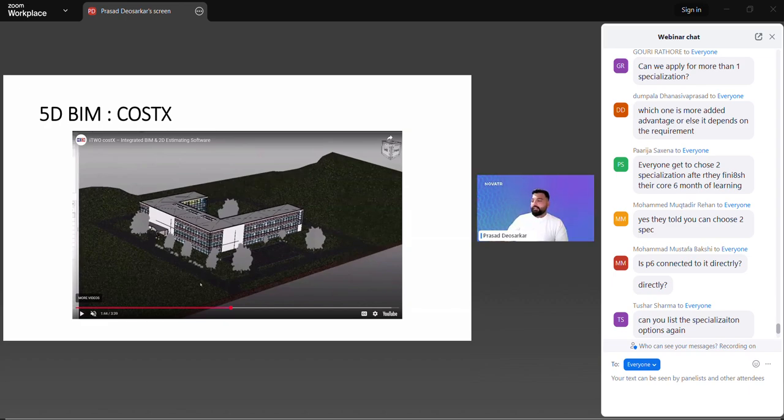If he has a BIM team and they have actually updated the as built status inside the BIM model, I could filter out all the as built elements from the particular site, and generate a quantity for all the as built elements in one go. I'm going to verify this quantity against the quantity that the subcontractor is claiming for.